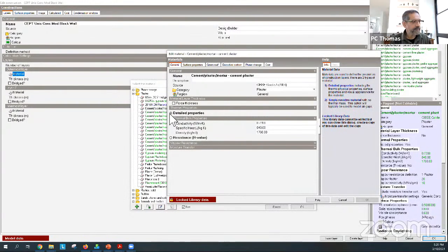Okay, so you should provide these conductivity, specific heat and density numbers if you want to create a new material. The only exception to that is if you are using an air layer between a construction. So for example, a very typical Australian British construction is 2 layers of brick with an air gap in the middle, a cavity brick construction. So in that sense, then the air gap is usually described by just an R value. Okay. Now you can read about all this stuff. If you pick up any of the books on this, you'll find it.